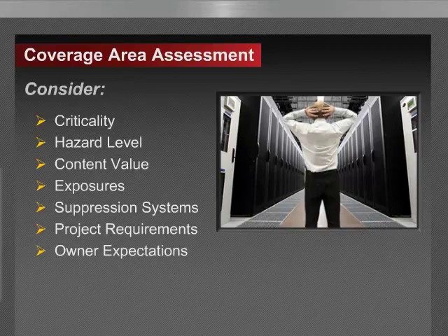Hazard level, that is, what hazards are present, such as combustibles, heat loads, and so forth. Of course, the value of the assets housed within the area. What exposures are there from adjacencies? Will a gaseous or sprinkler fire suppression system form part of the overall fire protection solution? And if so, will detection be required? And what are the project requirements and owner expectations?